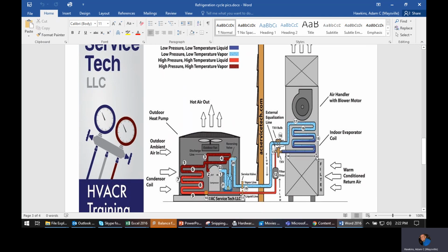I know rules of thumb are dangerous, but a basic rule of thumb is you want to keep 8 to 12 degrees of superheat. That's kind of just a good guideline. So what is the purpose of superheating refrigerant? Well, first of all, what is it? It's actually heating the refrigerant, adding more heat to the refrigerant beyond the point that it is completely vapor. So the evaporator is changing that refrigerant from a liquid to a vapor until it becomes 100% vapor.